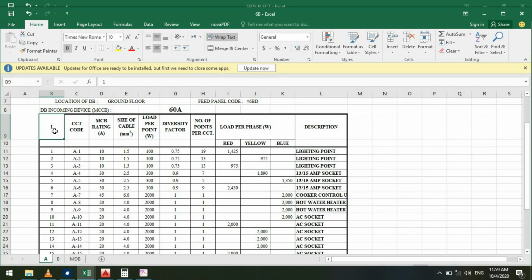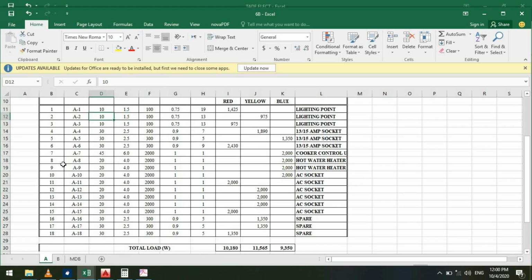Moreover, the circuit number is what determines the conventional name for a distribution board. For example, in the market, if they say D4 board, it implies it has 12 circuits. D1 board is 3, D2 is 6.